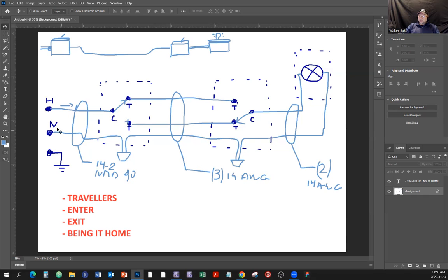So you're not going to try to run the whole thing, because it would take you forever and you would just dig yourself in. So in order to make things nice and proper, pull the wires, cut them off, pull the wires, cut them off, pull the wires, cut them off, and then, well, possibly label them. And then the next thing should be the termination of the wires. So that's why we got a pigtail here and make a pigtail right here.